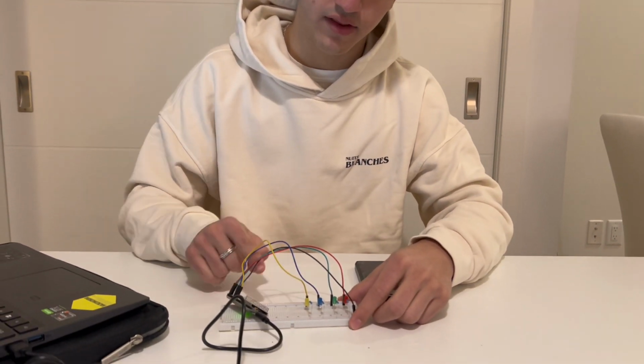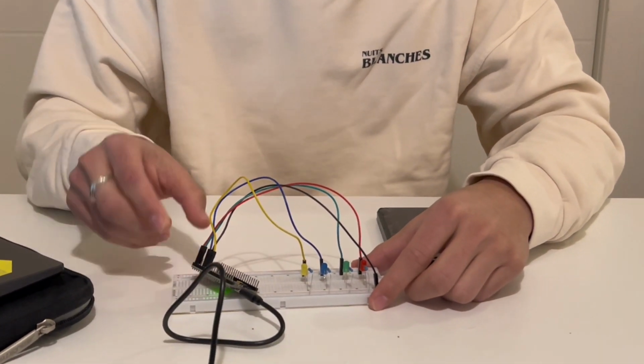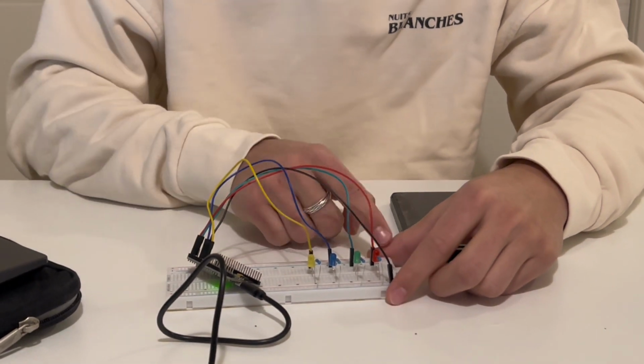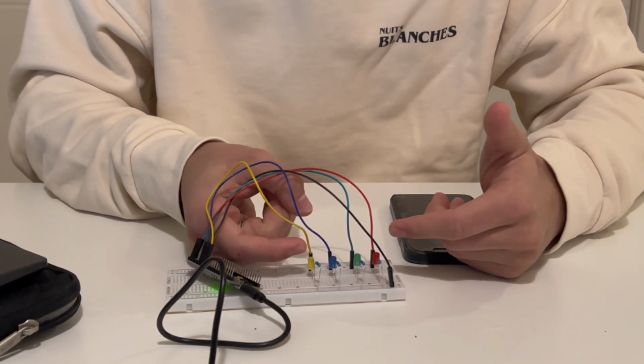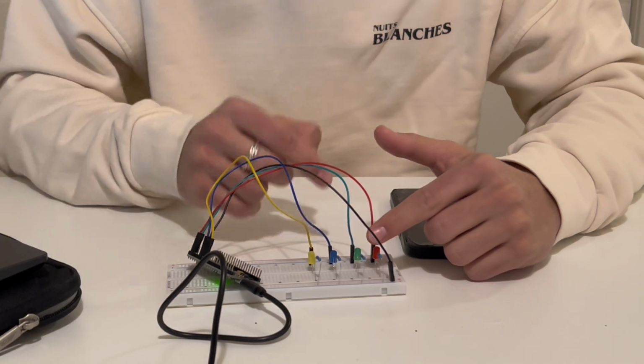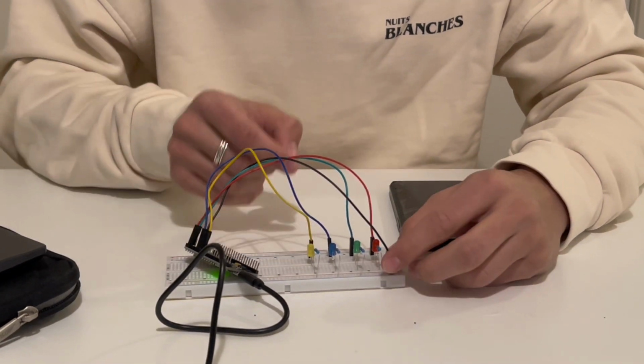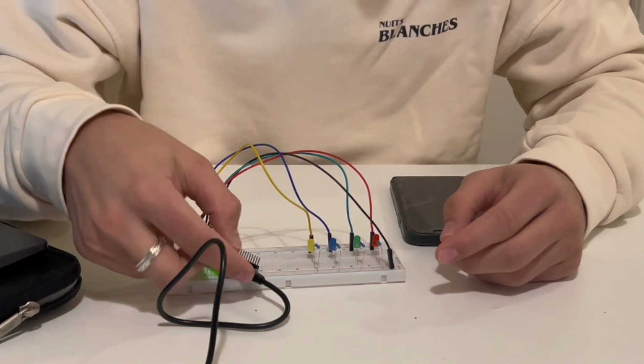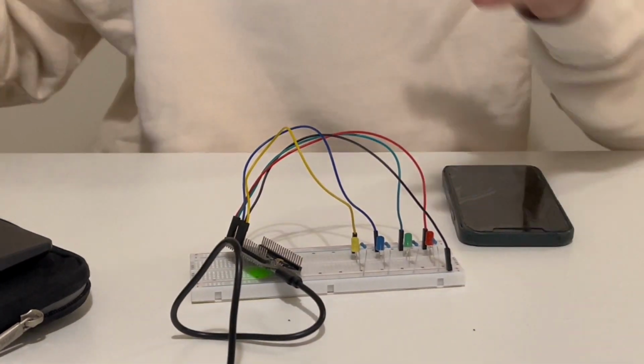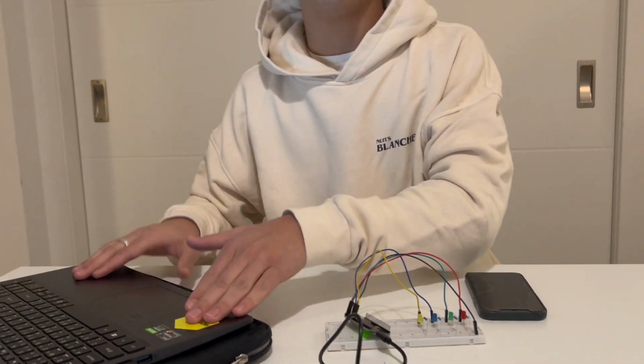For equipment and supplies, we will have, first of all, the Arduino set. Here you can see the breadboard, the controller, the ESP32, and 5 cables in total, one for each LED light. You will need 4 LED lights, 4 220 ohm resistors, and 1 ground cable. Then you will need a micro USB cable to connect to a laptop. You will also need a laptop on which you will download the Arduino software, and on your phone you will download the Blynk software, which will allow us to control the LED lights.